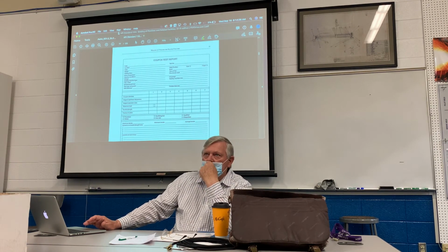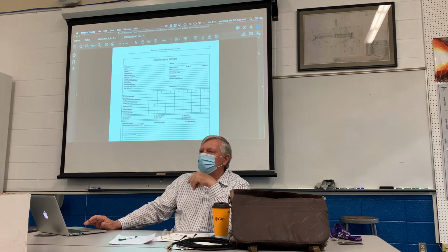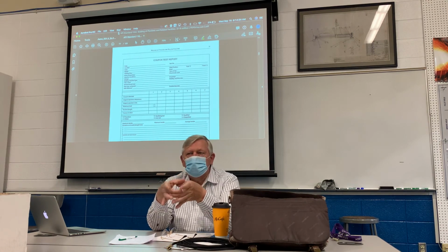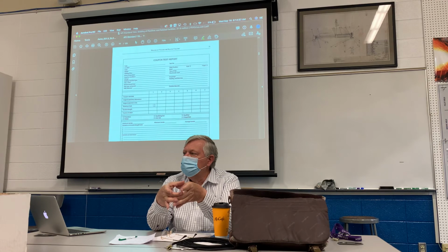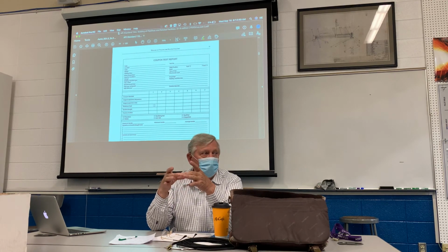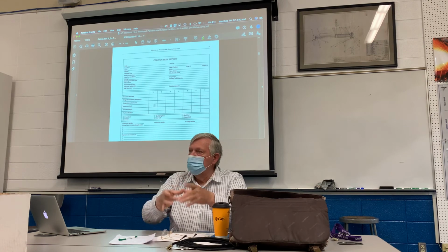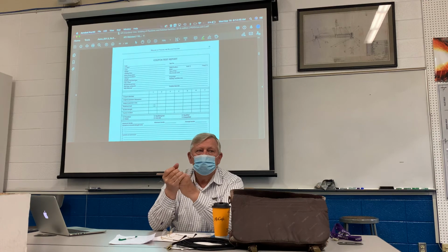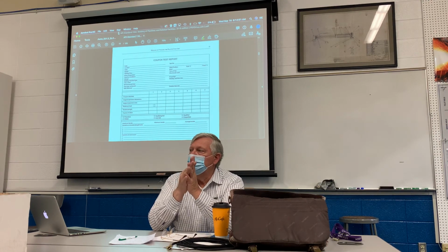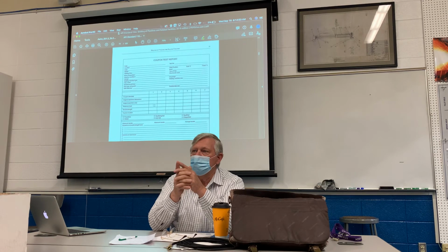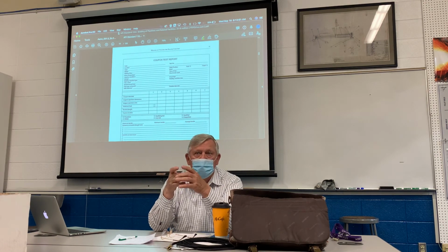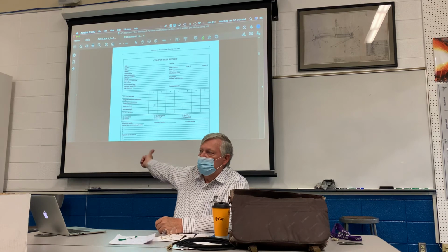And every tensile tester usually has a multiplier that you have to multiply it by. That multiplication number is basically the size of the cylinder. So if you have a 2-inch hydraulic cylinder ram that's doing the tensile testing, what's the square area of a 2-inch ram? Pi times the radius squared. So 1 squared is 1, times pi is 3.14, so you have 3.14 square inches. So you multiply that times the load to get the tensile.